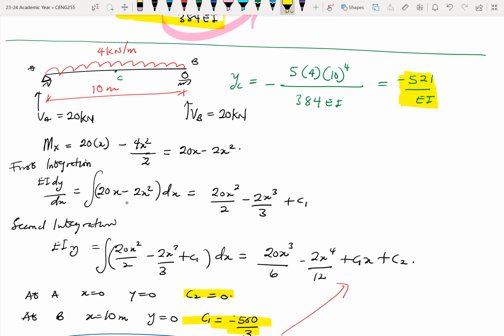So with the double integration method, we can look at it in this way. It is a pretty cumbersome equation method, in the sense that you need to know a few things. One, how to integrate. That is critical to everything when a double integration method works. And as the name implies, you have to integrate twice, which means that you have at least two constants to deal with, two unknown constants to deal with.